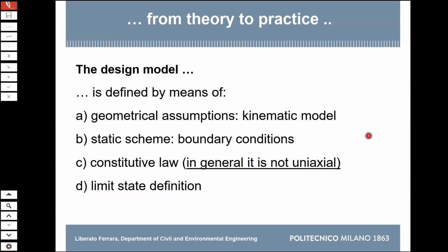So then there are the boundary conditions, as we have seen this morning for connections. The boundary conditions, when we design a support, a roller, a fixed edge, okay, for us it's an idealization, but that idealization has to correspond to something that you make in reality. And it's a twofold mechanism. You must realize something that respects your assumptions. But the way you realize it also determines how the stresses will go. So you govern, in a sense, the flow of the stresses.